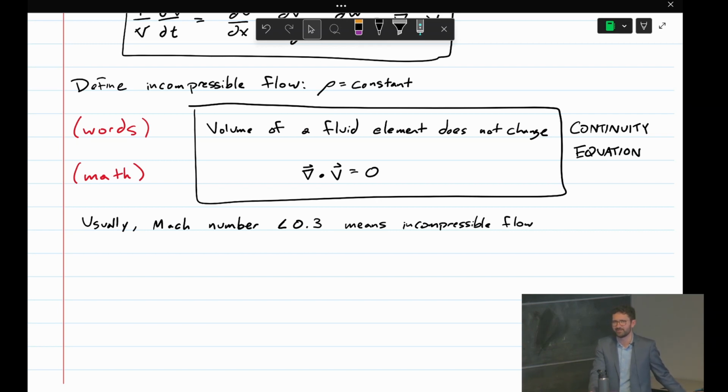Yeah, so we usually hear the Mach number in the context of aerodynamics, but it exists for any flow. We'll talk about what that is later on, but it's just about the speed of sound. So you might ask, how can we hear sound in certain fluids? The speed of sound is basically the speed at which information can be transferred in a fluid. So a small pressure perturbation can move through a fluid at that speed.